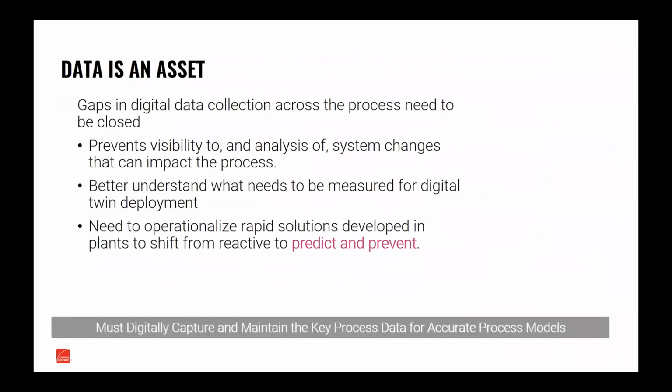We also learned a lot of lessons throughout this process. Although digital twins are a technology that can be useful in understanding your process, without data gaps being closed and proper maintenance procedures in place, process modeling is limited or not possible at all. You won't be able to calculate residence times if a data feed is unreliable or non-existent. In addition, any relationships that your engineers know exist on a fundamental level will be obfuscated if your data feed isn't kept in optimal shape.